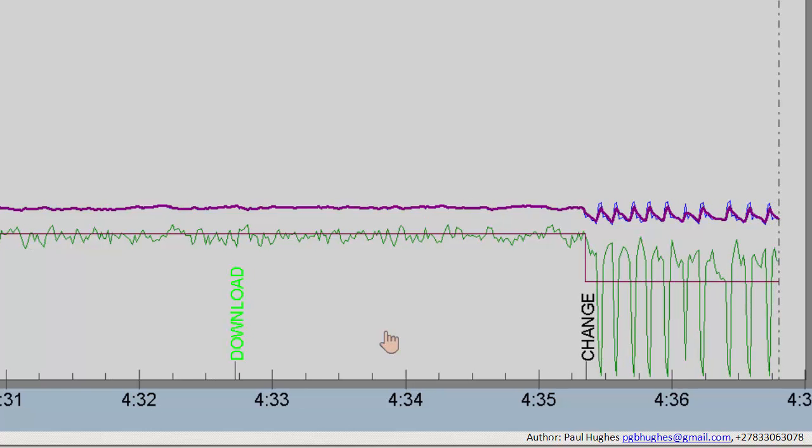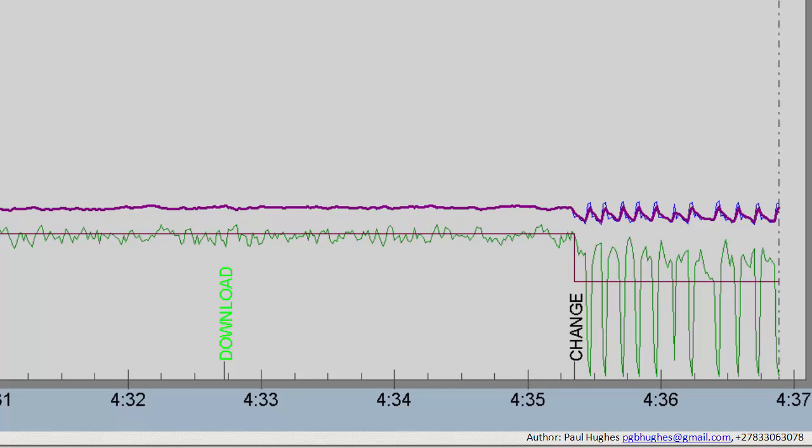So the blue line, which is superimposed, that blue line there is the output to the control valve. So you can see the flow transmitter responds fairly well. It's totally correlated, and because it's on the same scaling, it's almost shown overlapping the output. But because of the valve time constant, there's a filter in there.